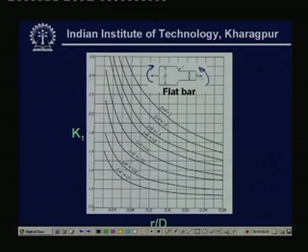That means, for the same type of flat bar, once you use a bending moment, you find different K factors, as over here we have a tensile load. If it is in the torsional mode, you will get again similar stress concentration plots.